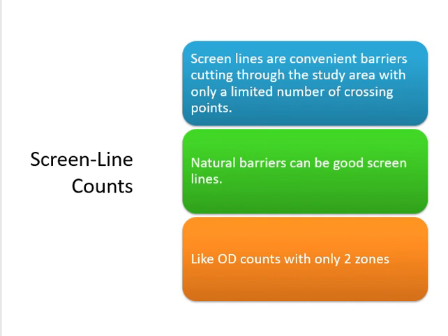What was the point? The first point was you make the cordon not here but here. The cordon should not cross from here but should cross from here. What is the difference between this and this? Why not here? More complicated because of the intersection. Same thing here. You will make the screen line. Again, it is imaginary. You will make it on the map. When you are making it on the map, make it on the road, not on the intersection.